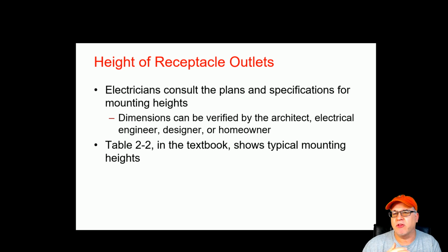But don't worry, either the plans will give you some ideas or you will just know it as you start to learn your placements, okay? But typically the height recommendations might be 16 inches to center or 16 inches to the top for receptacles. That's from the finished floor. All those types of things are discussed in the program, but you'll get a kind of a flavor for how you like to do that. Just remember that you do have specific height limitations on some things.